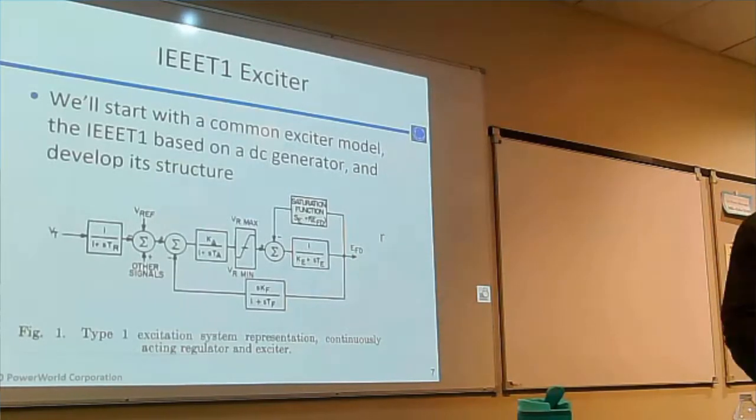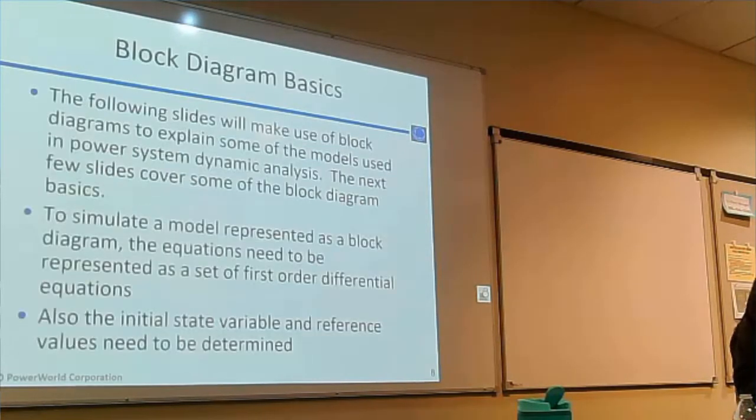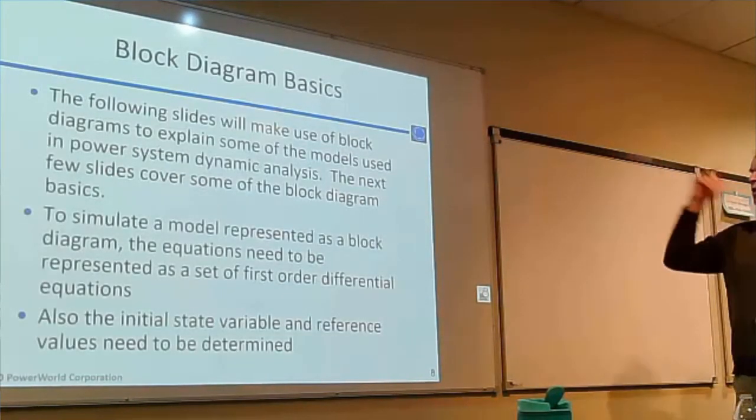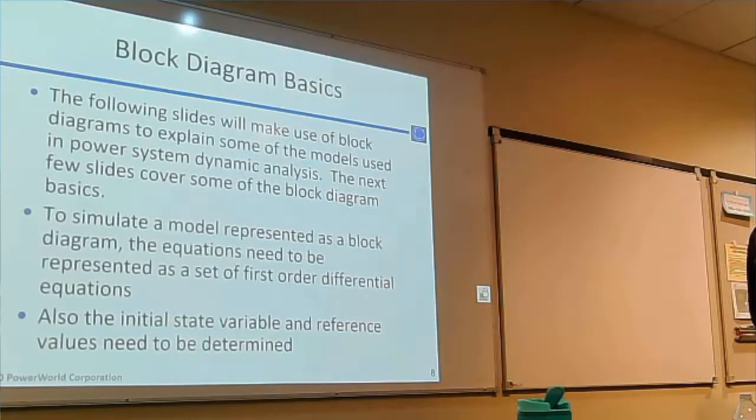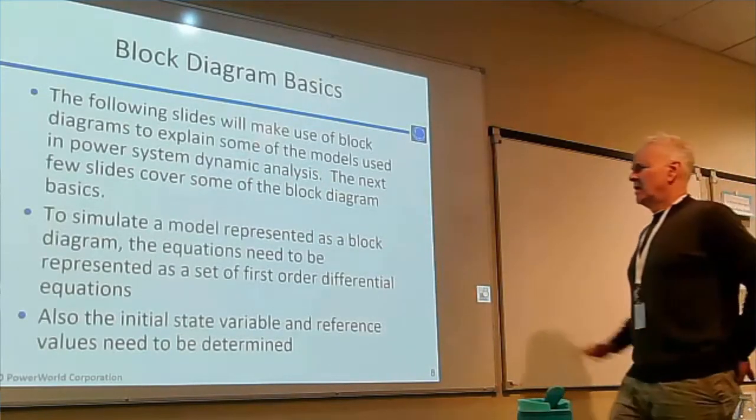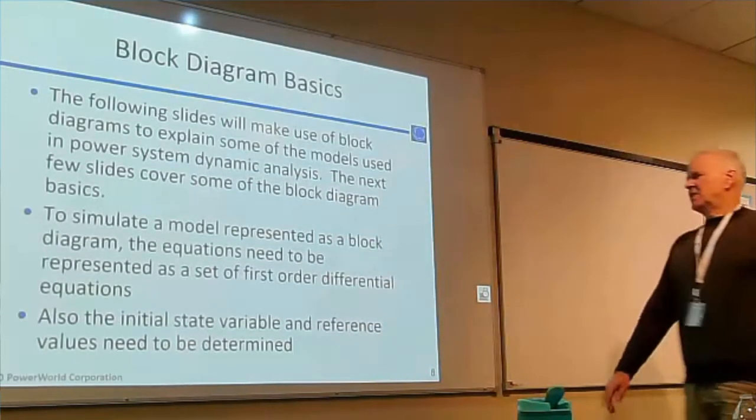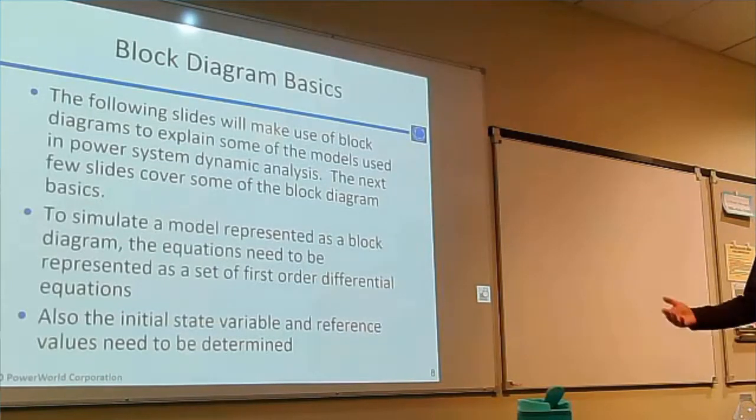And we'll go through this in a little bit more detail in just a second, but first I want to go through the block diagrams. So I'm going to make sense of the block diagrams here that will be used throughout. To simulate a model represented as a block diagram, the equations need to be represented as a set of first order differential equations.